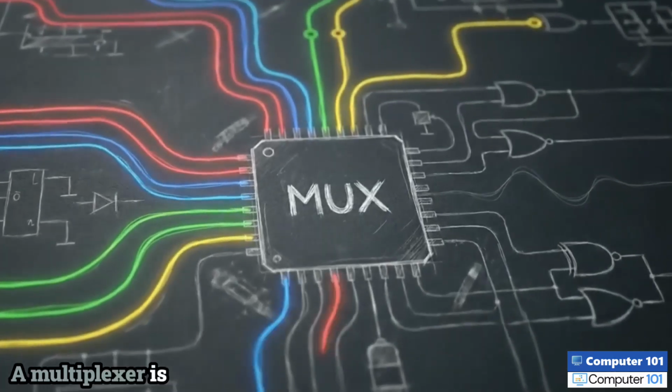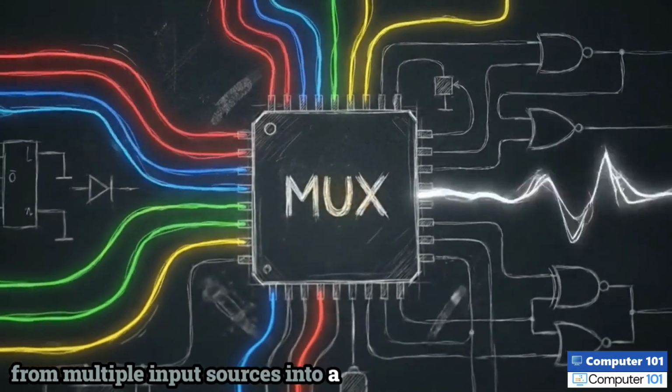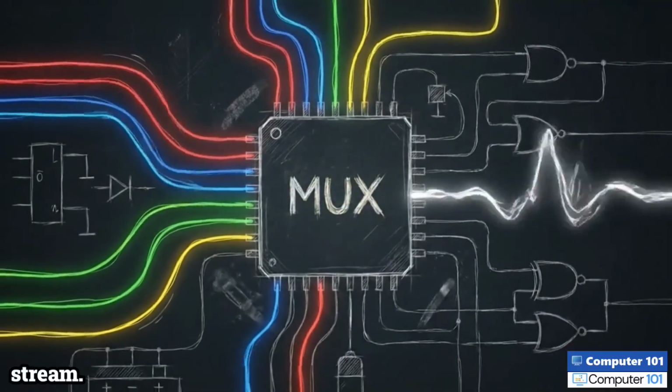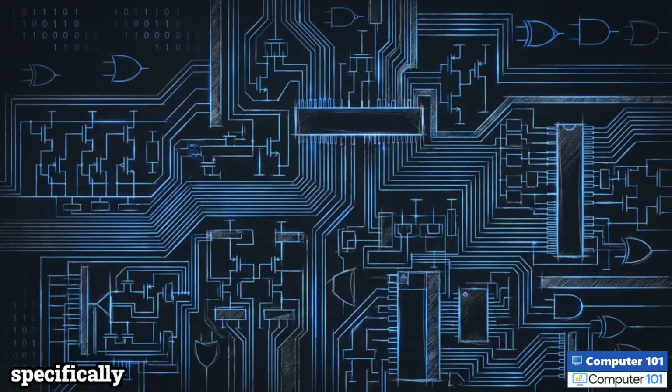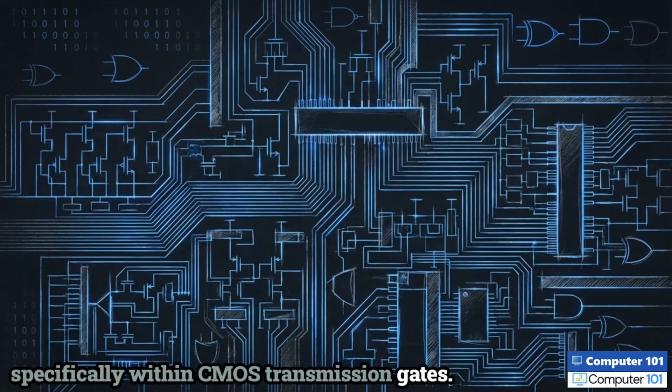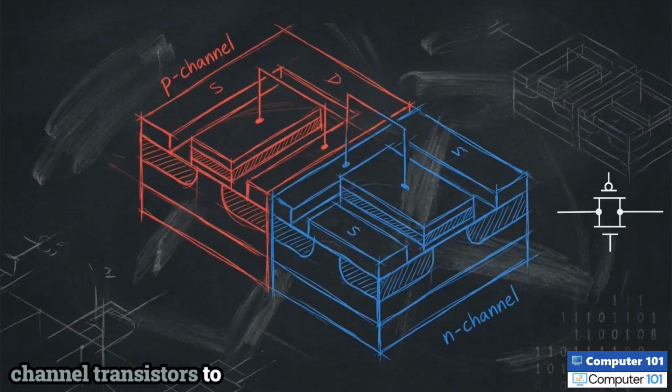A multiplexer is a digital switch designed to route data from multiple input sources into a single, unified output stream. This routing capability originates at the physical layer, specifically within CMOS transmission gates. These components are built using paired P-channel and N-channel transistors to create a controlled pathway for electrical signals.